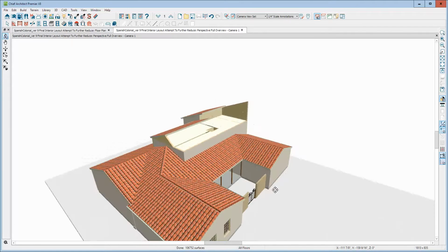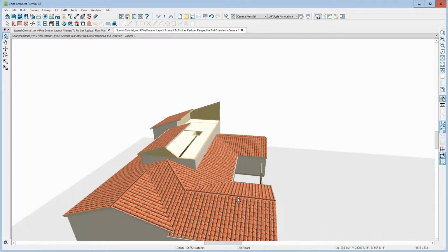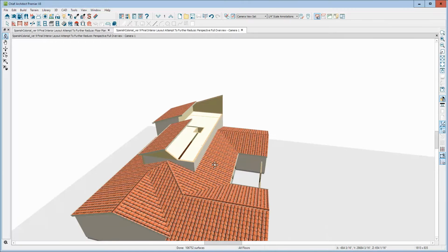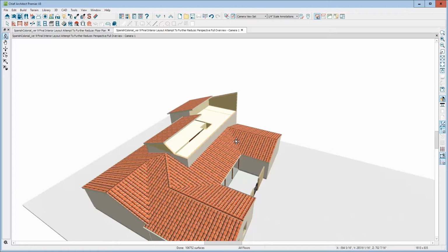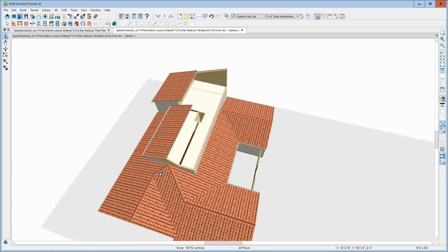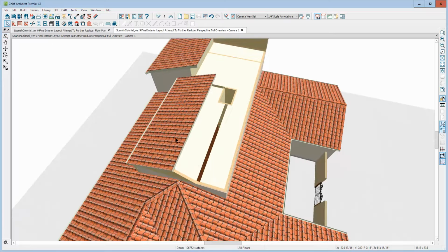The thing about Suite is it's very limited in what it will and can do. I'm sorry, but that's the case. I looked at this in Suite and went, oh, the devil with it. If Suite can't figure that out, it's not that complicated. If you got your ceiling height set properly, and I suppose you do, it just keeps saying can't produce a roof plane. Well, what are you going to do? What I'm going to do is just fix it manually. I'm in Chief Architect X8 and I'm not limited by the limitations of Suite.